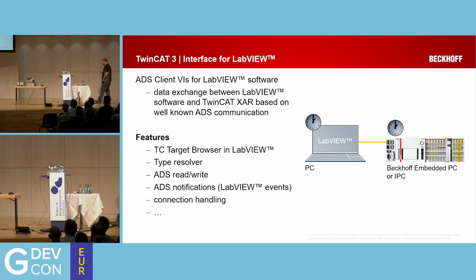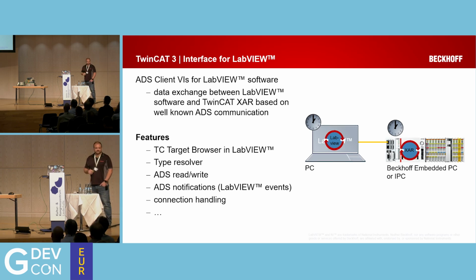Again, surprisingly for this demonstration, I chose to use the Beckhoff product, which is a VI library called TF3710 that allows us to communicate with Beckhoff IPCs over this ADS system. Now, ADS is a really nice real-time to non-real-time communication protocol. It allows us to string Beckhoff PCs over large networks of IT infrastructure networks and then pass data back over ADS to databases, HMIs, etc. In this case, we chose LabVIEW because then we could do the analytics piece.